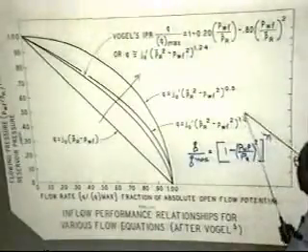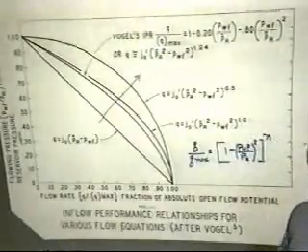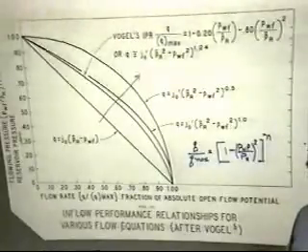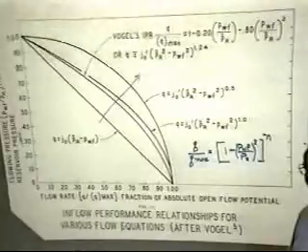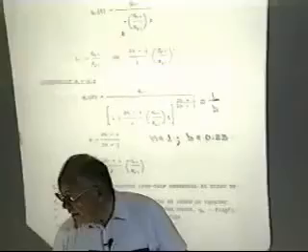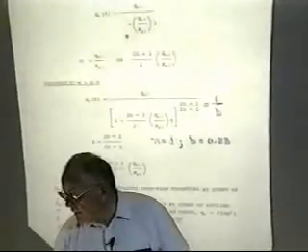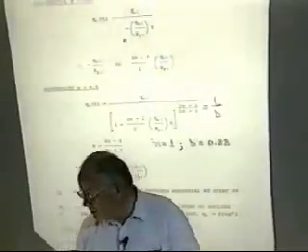In lieu of ever running any multipoint data, just use an N of 1. That'll at least give you the same type of inflow performance relationship as you'd get if you use your Vogel's curve. I took different forms of material balance equations. This is what I get for solution gas drive.